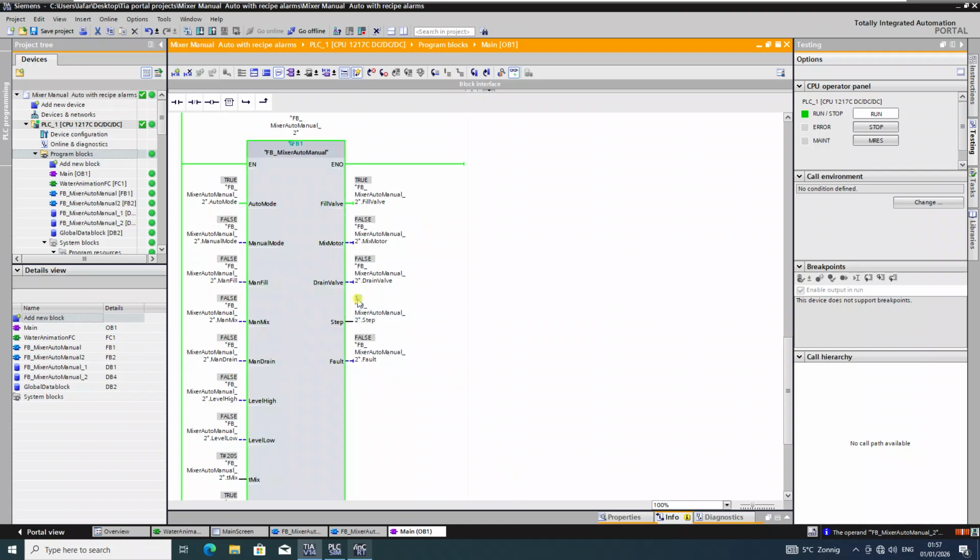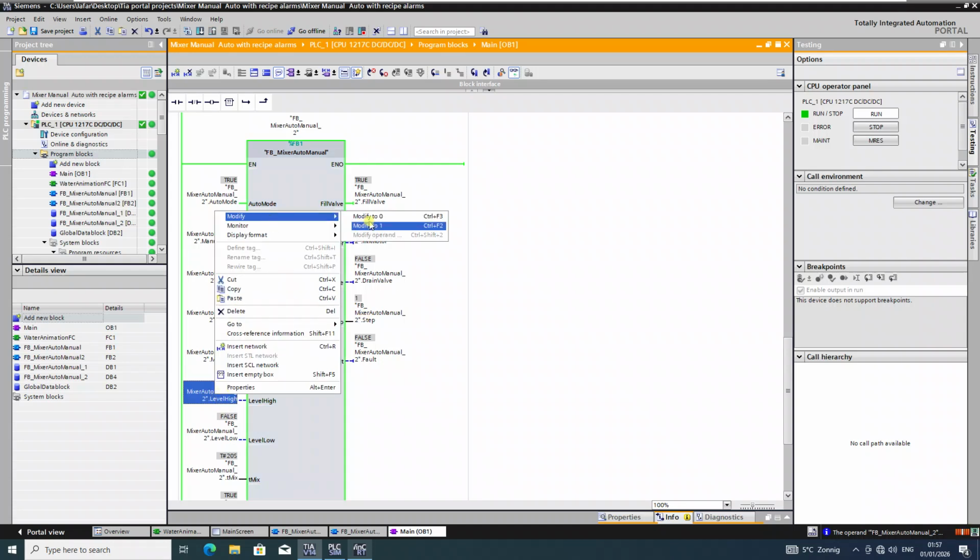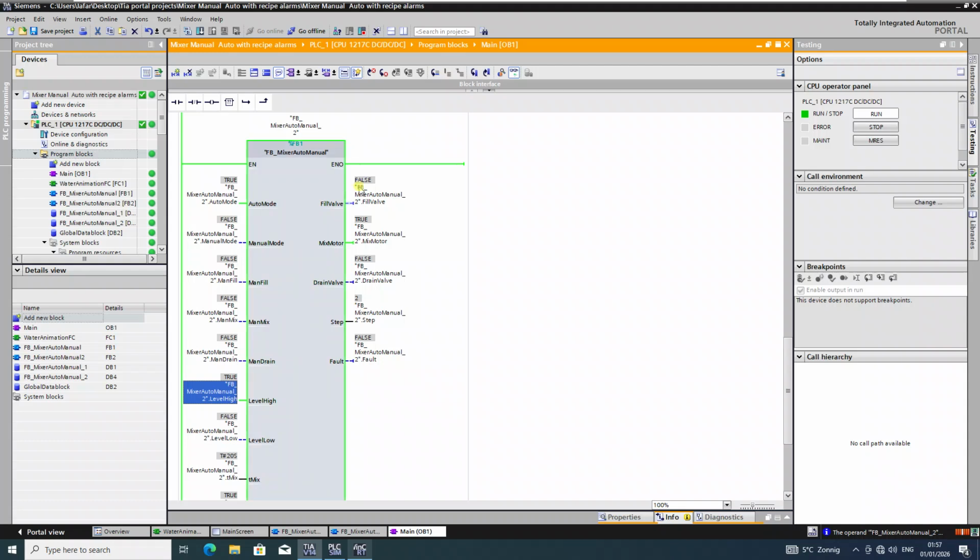When the high level is true, and the step is also now in 1, filling is off. Now it's mixing 20 seconds, and after 20 seconds the mixer is off, it drains to level 0. Drain is off, everything falls, step 3.